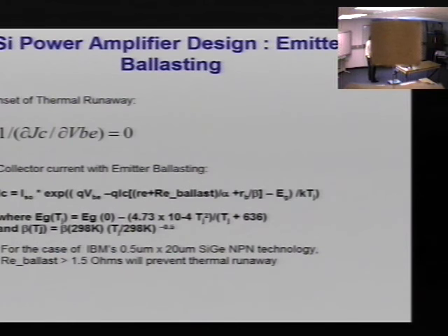And for IBM's technology, if you're ballasting with an aggregate resistance of 1.5 ohms, it turns out from the simulations, and also from measurements, that 1.5 ohms would be sufficient to prevent thermal runaway.